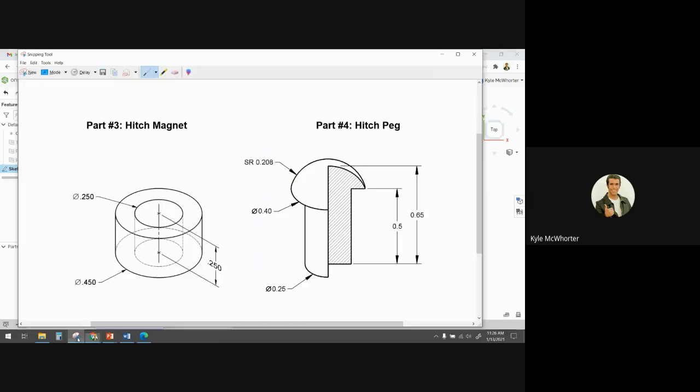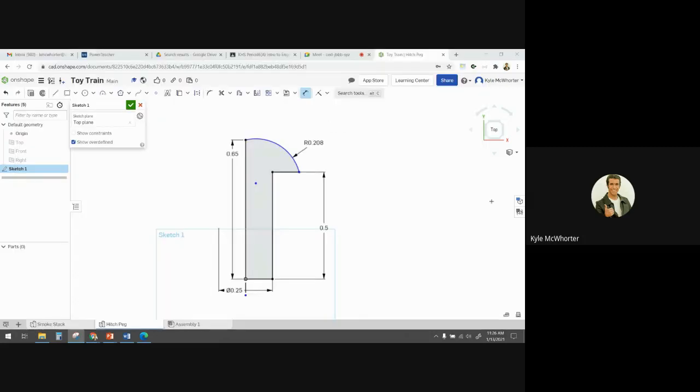And then this diameter out here is 0.4. So I would measure from the outside point here to the construction line, go to the other side to place it so that it's measuring a diameter, and that was 0.4. And now you can see that everything has turned black, so it's all fully dimensioned and constrained.